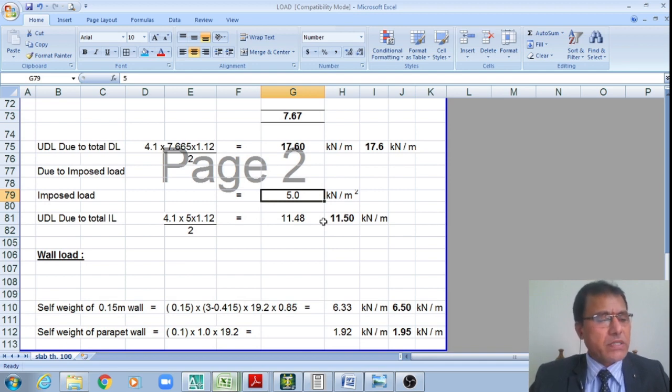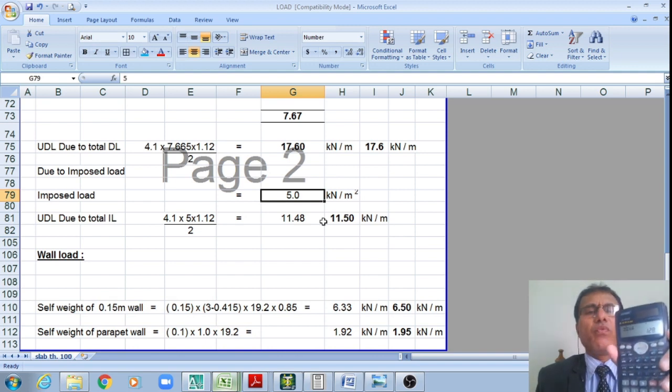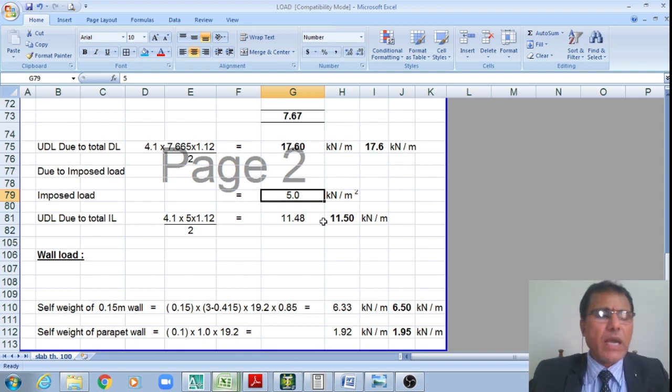Actually for these just 8 flats, 8 multiplied by 4, 32 flats, overcrowding will not be possible, because in total over 32 flats, even if in each flat there is one couple along with 2 children, that is 4, 32 multiplied by 4. Therefore at maximum 128 people will be using, or at maximum not more than 150 people will be using. Therefore it will not be liable for overcrowding.